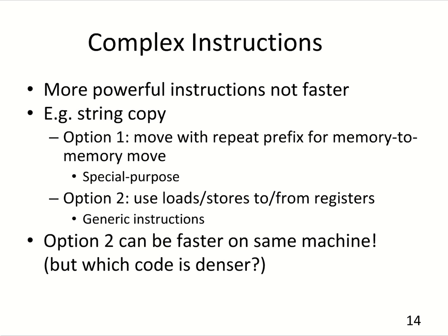And in scenarios or environments where the size of the instruction memory is actually very important, perhaps because there's simply a fixed capacity available, or because of energy constraints, accessing a larger memory is going to consume more energy, that smaller footprint might actually be the better engineering solution for that particular environment. So the bottom line here is it's not always immediately obvious which is better, and you really have to do the careful trade-off analysis each time.